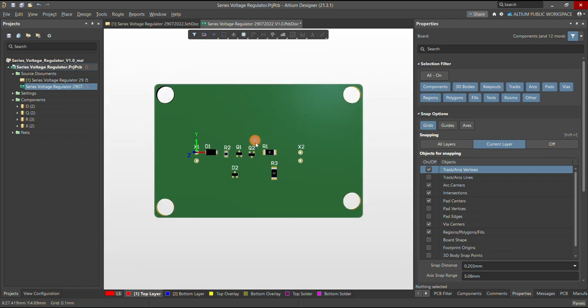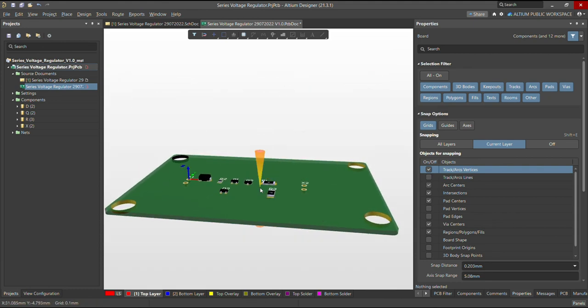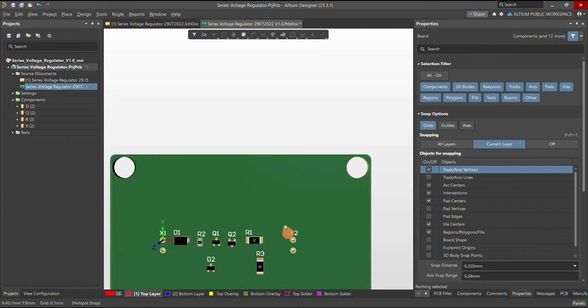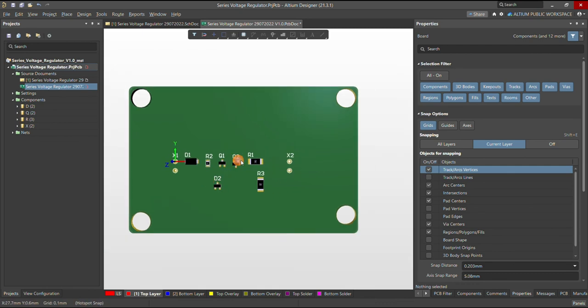Yeah, so that's how you can import step data and do such kind of modifications, and change your stack layer. And you can see that here the stack layer is also proper, and you can change the shape of the board.